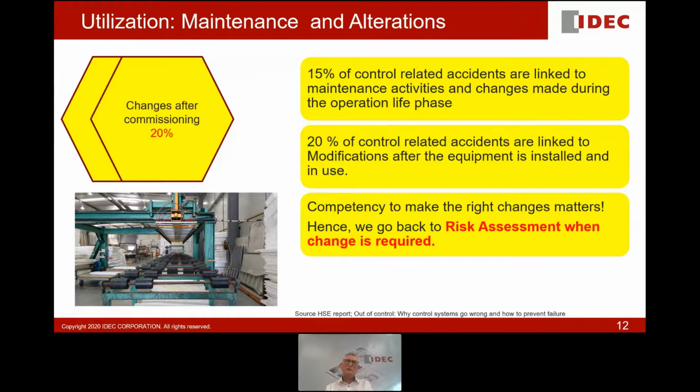But changes made after commissioning, modifications and upgrades, the addition of another machine downstream. This is where we see 20% of safety-related accidents on the control system. That is really, really a concern. And it is for that reason that competency, following the standards, making sure that you are actually doing it compliantly is really important. And hence we go back to the risk assessment, because if you're making a change to a machine, it's quite likely that the change you have made was not in the scope or vision of the person who originally designed that machine or designed that line.